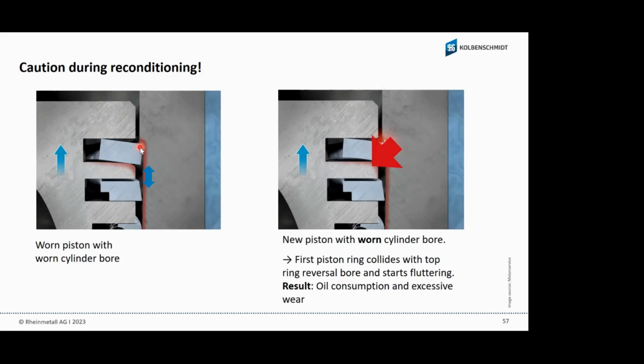One reconditioner called me and asked me, Rainer, what do you think? What happened? Because the oil consumption has increased. But I changed only the piston and the piston rings. And I asked them, did you check the cylinder bore? Yes, I had a little bit of wear on it, but I thought it was okay. I said, what do you want to hear from my side? I know it. It was my fault, Rainer.